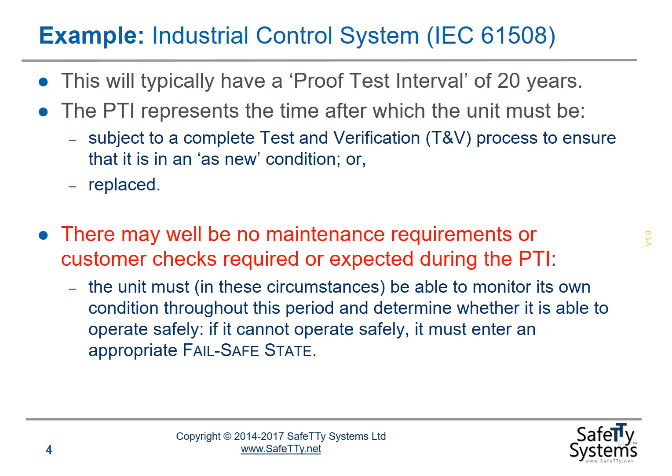There may well be no maintenance requirements or customer checks required or expected during the PTI. The unit must, in these circumstances, be able to monitor its own condition throughout the PTI and determine whether it is able to operate safely. If it cannot operate safely, it must enter an appropriate fail-safe state.